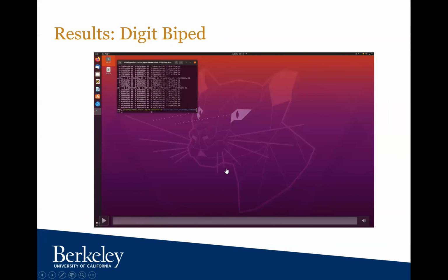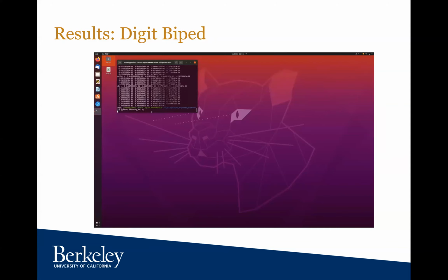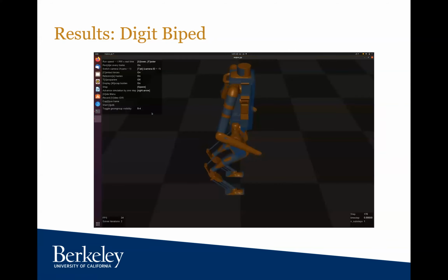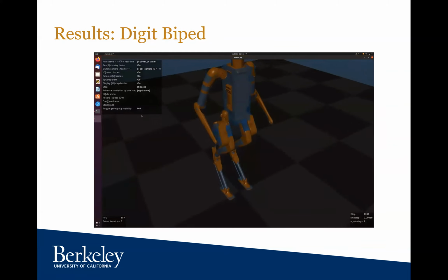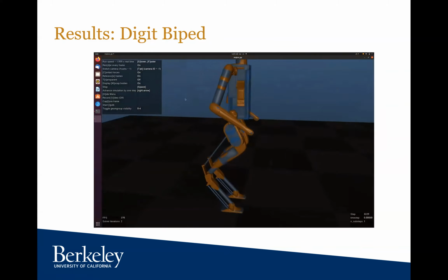While Pyomo is good for quickly setting up an experiment, its runtime is too slow. That is why for controlling the bipedal robot we used OSQP. It's a much faster solver. Adapting our quadruped MPC design to fit the biped, it is now solving 4 reaction forces per foot and 8 outputs total.